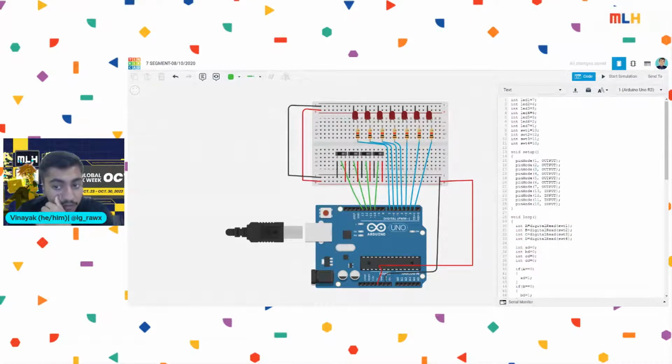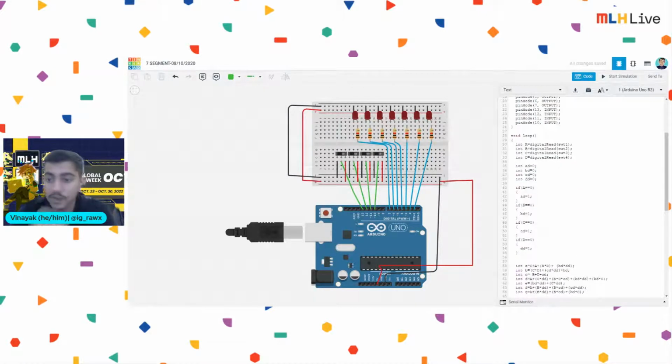Once we have done that, we have also set the input and output modes with the registers we have connected. For each LED we have a different register, and we have connected all the output modes the same way. Then we have marked the digitalRead command. The switches need to be read. Why does a switch need to be read? That's a good question. Your system should be able to identify that if a switch is open, what the next instruction is going to be.